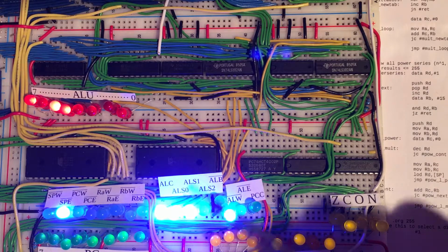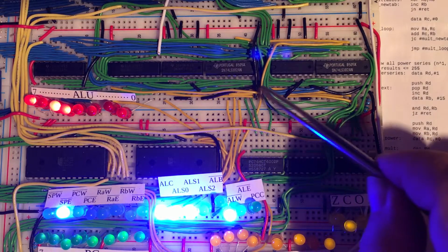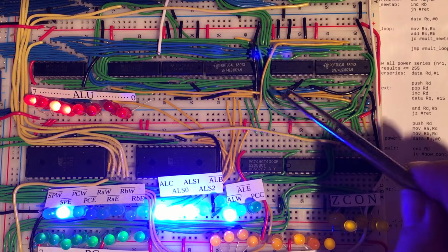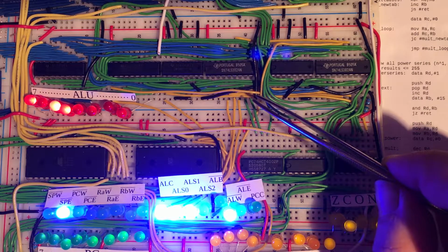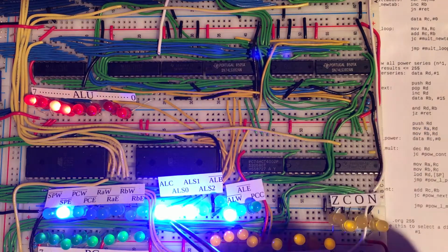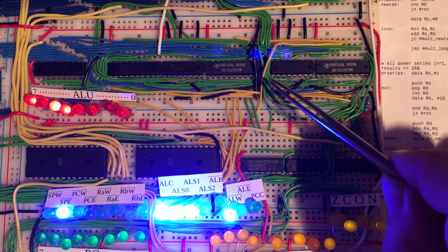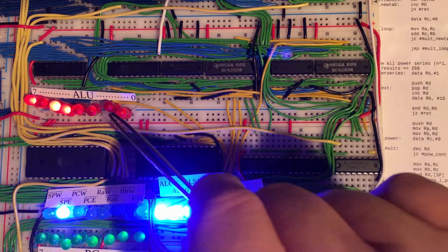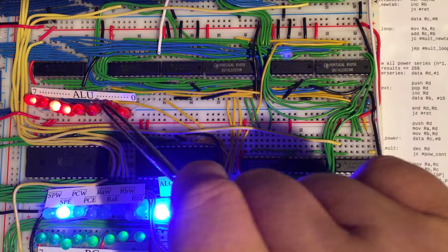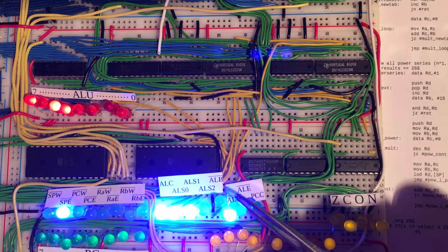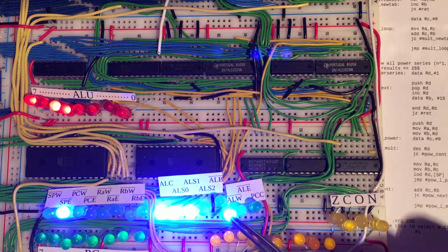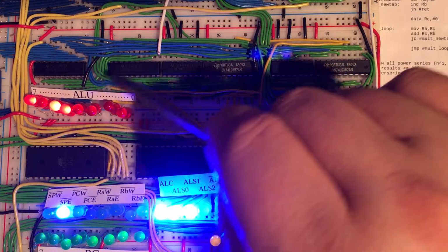But for now we'll just accept that those 4 lines go to the calculation unit and simply tell it what to do with its 2 operands. And the result of its calculation, based on these 4 lines, is then latched into this register whenever the control logic tells the ALU to write to the ALU register. So here we have the write and the enable signals for this register.